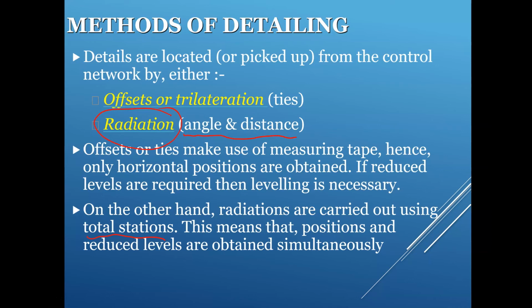You've got to limit the distance though, because the longer the line that you measure with a tape or some sort, error will crop into your work. So limit it to maybe about 5 meters or so. But then again, that's not a rule. There's no rule about that. It's just a personal choice.